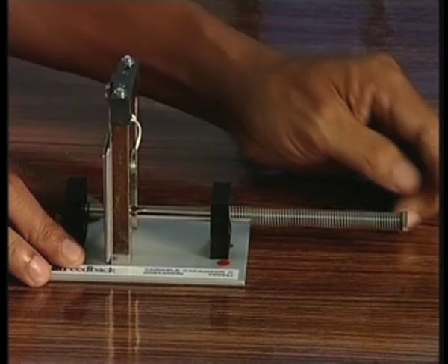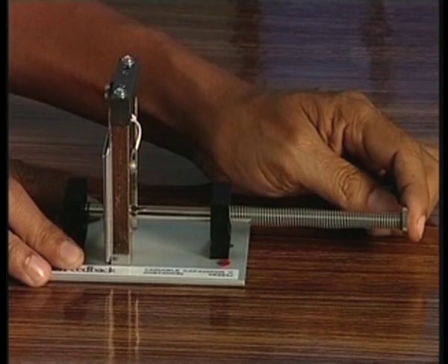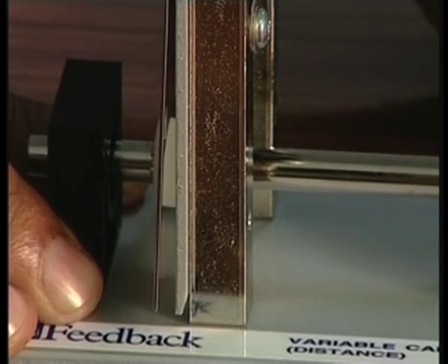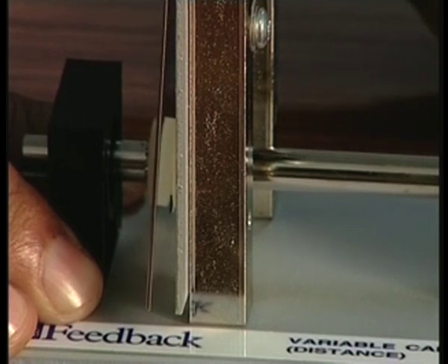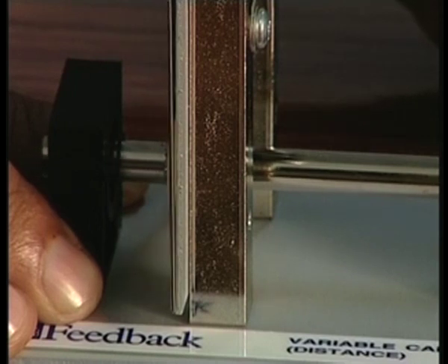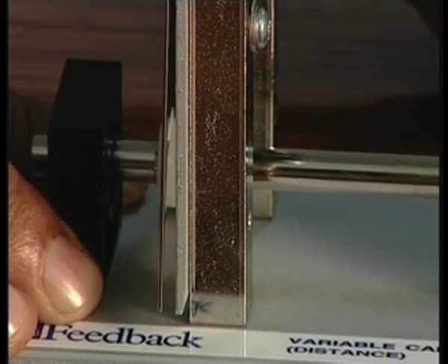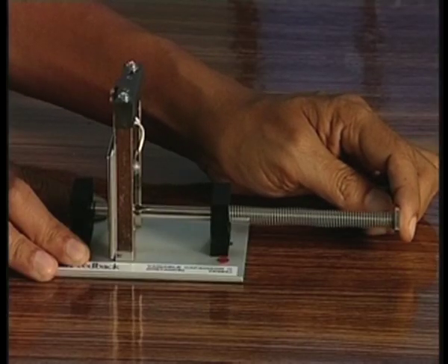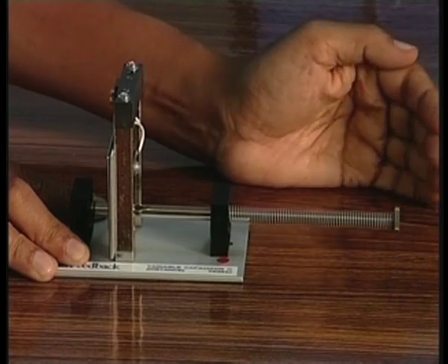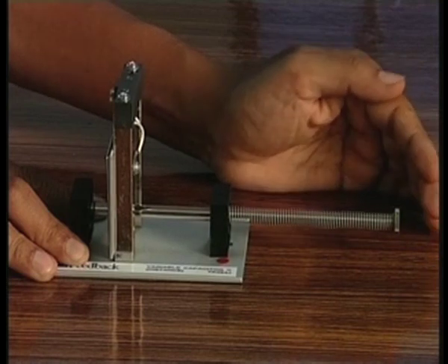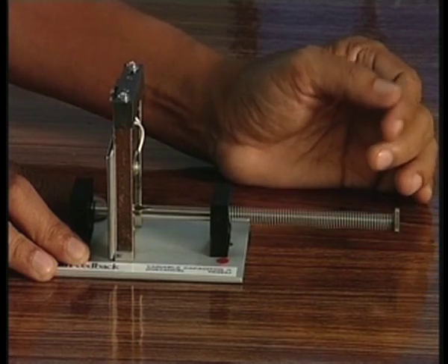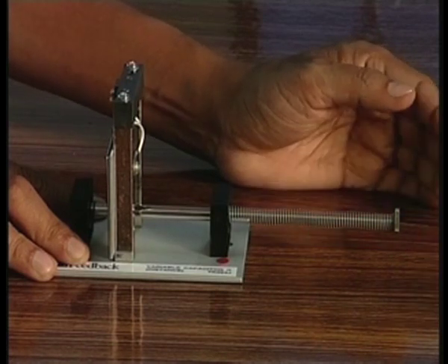You see, if you make the displacement here, the separation between the capacitor plates changes. So obviously, if the separation changes, the capacitance value also will change. So if you put it in a bridge, obviously the bridge unbalanced output also will change. That bridge unbalanced output can be calibrated in terms of the displacement, because ultimately we are not measuring the capacitance, we want to measure the displacement, which is our input, that is converted to the variation of the capacitance, and ultimately gives you some unbalanced voltage. These are other applications of the displacement sensor based on capacitance.